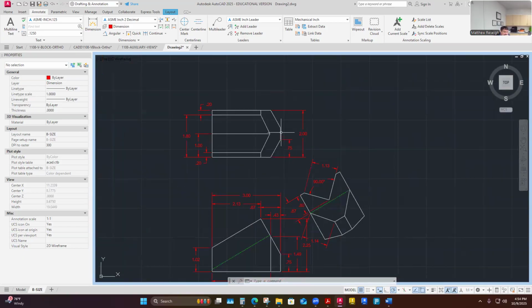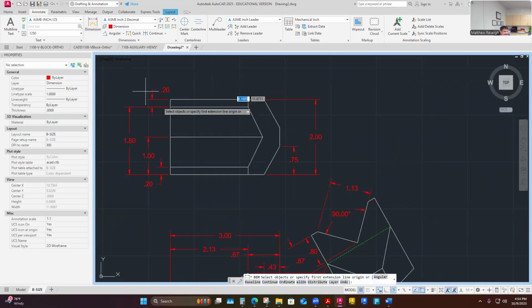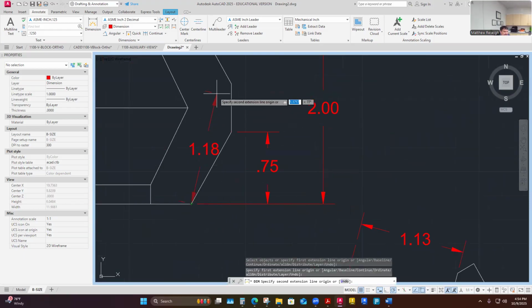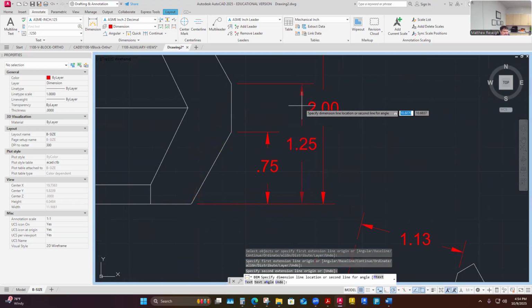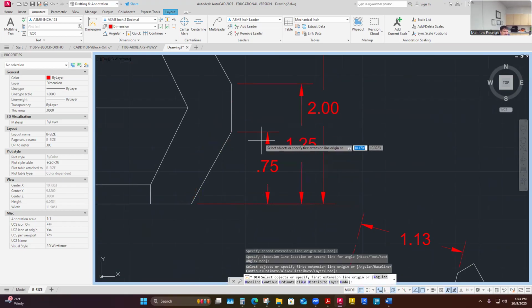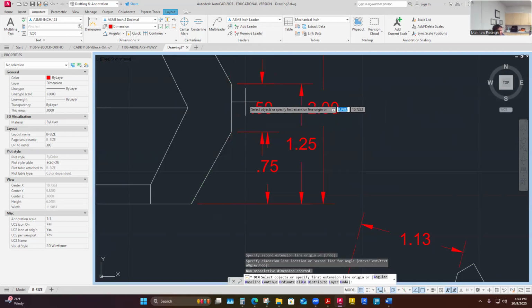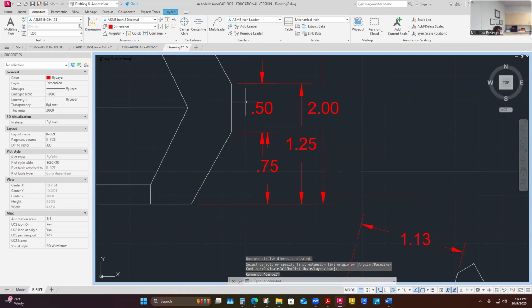But I need this dimension here. I feel like the front is going to be the best. So this is another case where, if this is really my control front side surface, then this would maybe be the best dimension to pull, 7.5 and then 0.25. And then if I really wanted to include this, I would include it as maybe a reference dimension. But either one could then become the reference dimension, right?